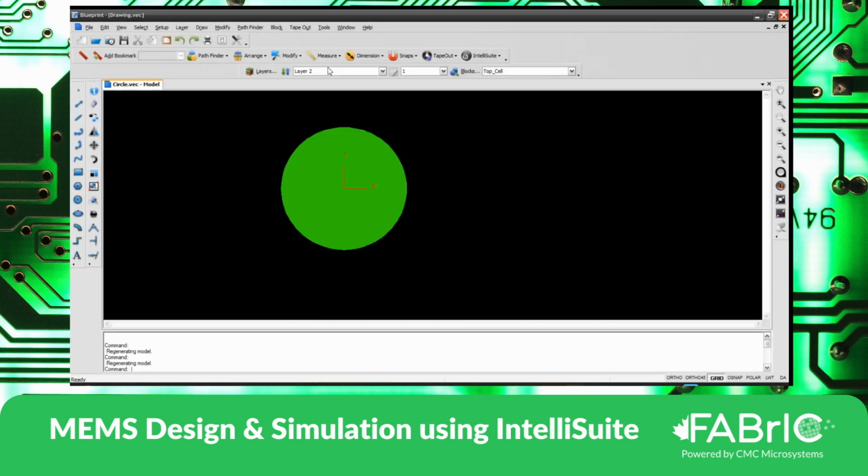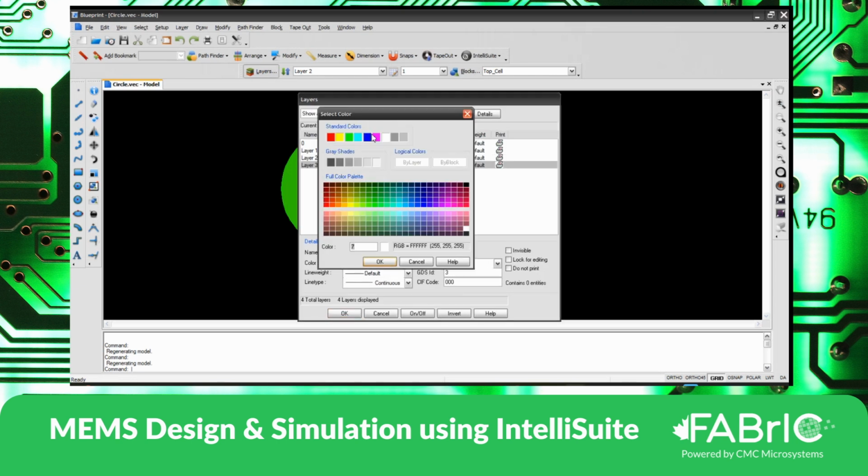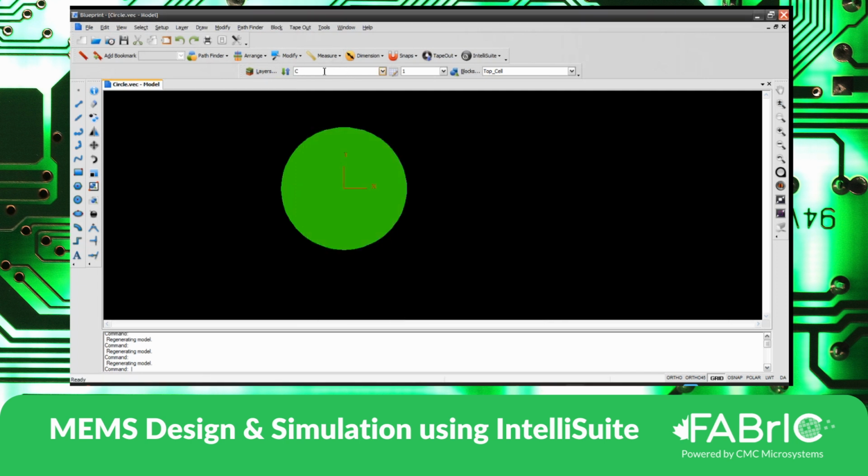Okay. Say I would have one more layer that is added here. For whatever reason, I will say this is layer A, this is layer B, and this is layer C. Okay, so now it's important to have a unique GDS ID. Make sure that it has unique GDS ID or else it won't import into 3D Builder. Okay, so now we have A, we have B, we have C.